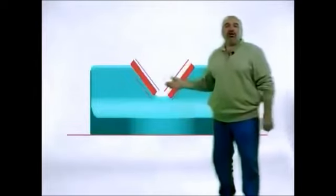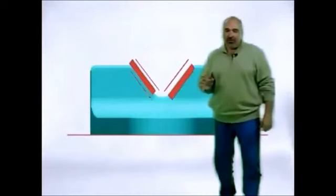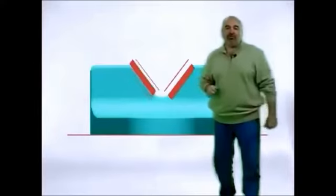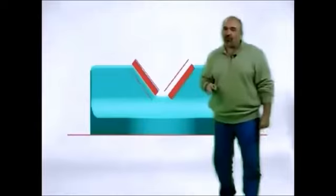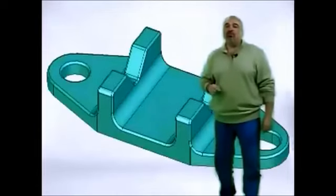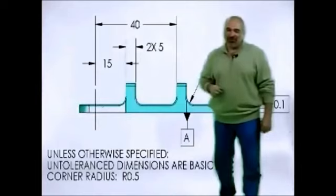Here the angularity tolerances float independently within the profile of a surface tolerance. Since angularity does not locate, the angularity tolerances float separate from one another. In order to have them float as a pattern, a composite profile tolerance should be used rather than angularity. But that's another tip for another month.